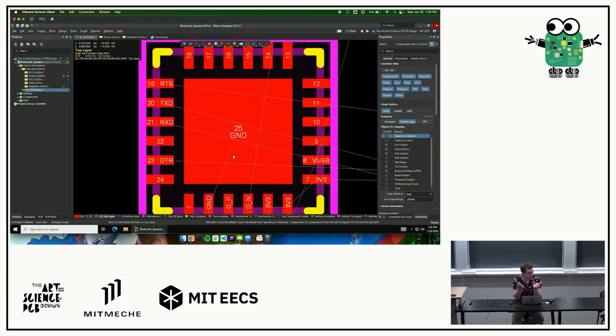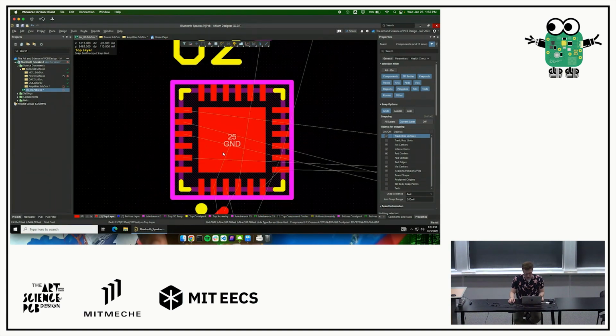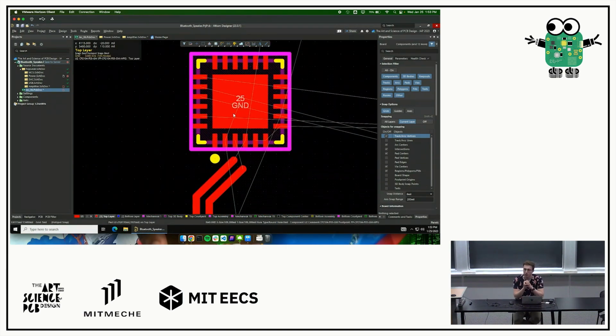Does that make sense? Sweet. Yeah. One thing you could do if you wanted to, I wouldn't suggest it, but if you really care about getting that differential pair the exact same length, sometimes what people will do is, if you have a through hole connector for your CAN bus on one side, or your differential pair on one side, and you take that chip and put it on the bottom of the board, that will flip the leads of your differential pair, and then you can route it straight.